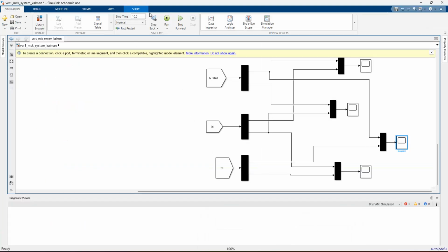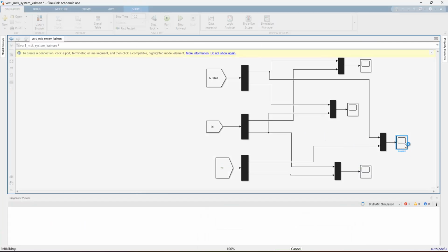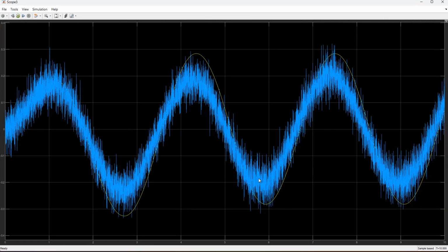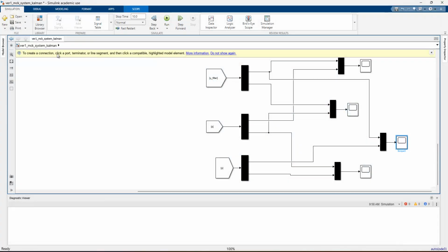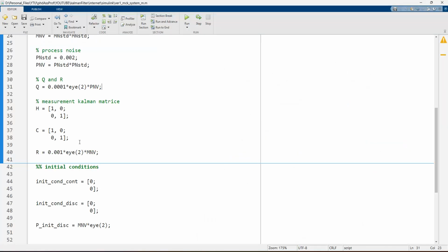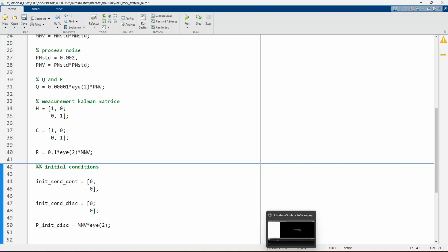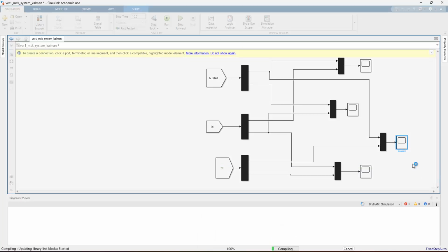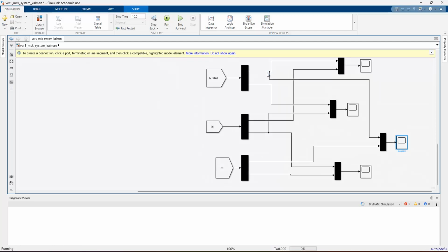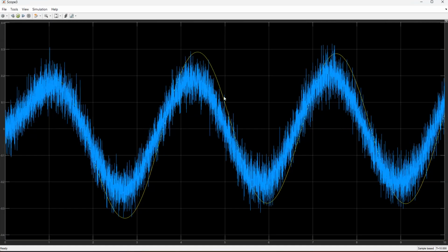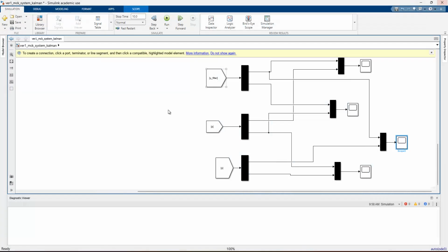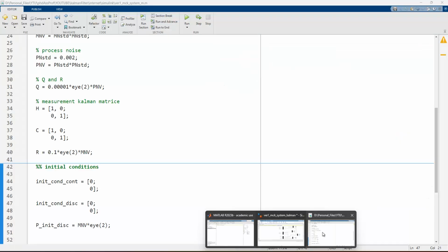And if I rerun this code, just see that right now, these two signals are closing to each other. And also we can set different values of this one. That's the Q, and R is set, and the Q is smaller and smaller right now. If I rerun this code, this position Y filter, the filter signals, and the noisy signals are closing to each other. For the worst case, just see that.